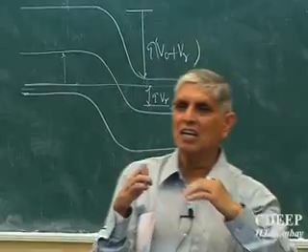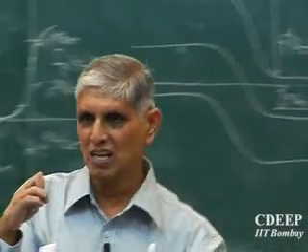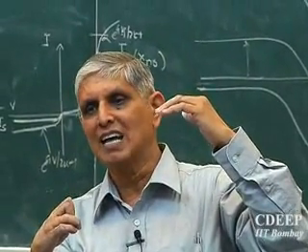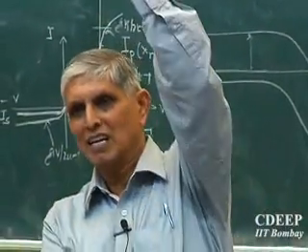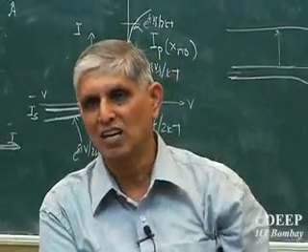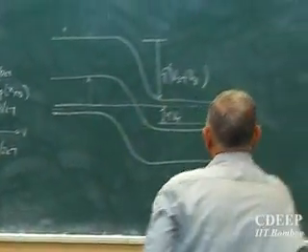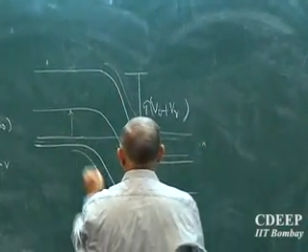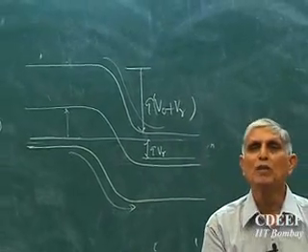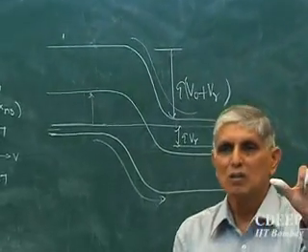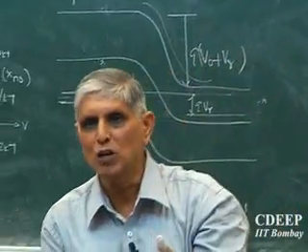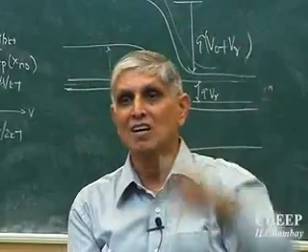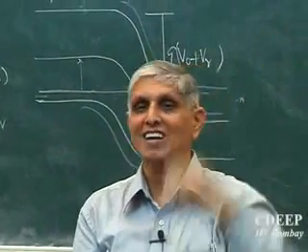So that means the change from EFN to EFP is qVR. Earlier, how was it? Electrons went up, holes came down. Now we reversed it, we reversed the barrier, so the Fermi level in P type must be higher than N type so that the barrier energy is now enhanced. This means an electron to come here or a hole to come here will be even more difficult. To diffuse, V0 was already stopping it. Now we have further enhanced it, made it a hill.